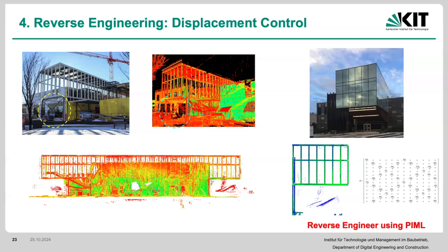This way, as you have a dynamic load that is going to be passing your infrastructure, you would have good hourly or daily information about what those load changes and what those displacements are, and does it actually comply with what you would get from reality through the strain gauges. And if these two don't match, then we're going to have to look a bit deeper into it and have other types of analytics, okay? So anything that we're doing has to serve some purpose, okay?